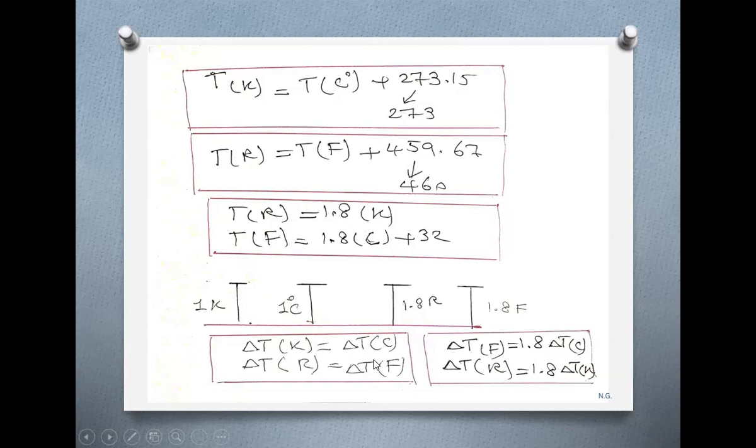So here, delta means the difference. Difference in temperature. So how do you read it? Difference in temperature in Kelvin is the same as difference in temperature in centigrade. I just explained. T1 and T2 are both centigrade. The difference between these two, for example, 40 degrees centigrade and 30 degrees centigrade. What is the difference in temperature? 10. Difference in temperature in centigrade. What is the difference in Kelvin? Okay, you add 273 to each, one of them is 10, one of them is 30. You add 273 to this one, 273 to the other one. They cancel out. So the difference of temperature in Kelvin is the same as the difference in temperature in centigrade.